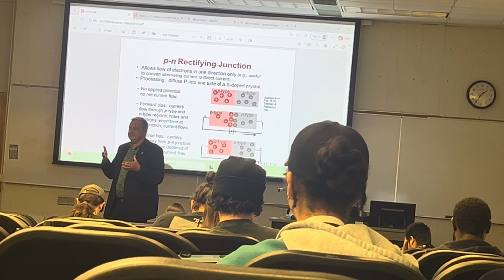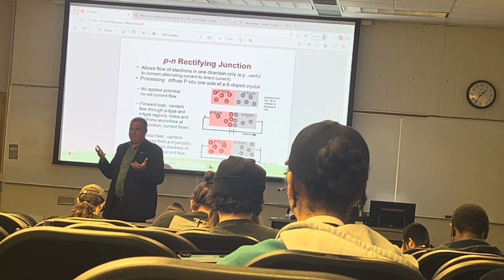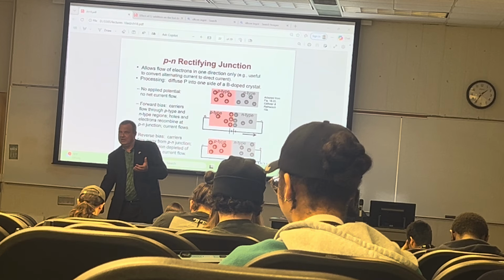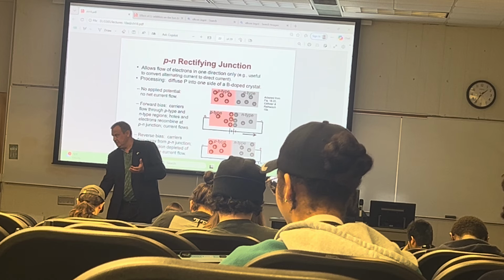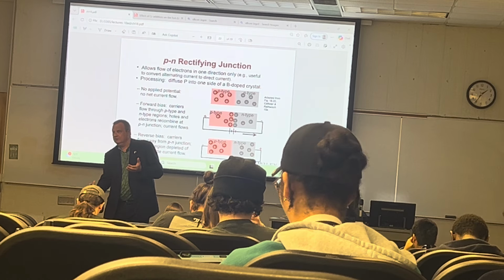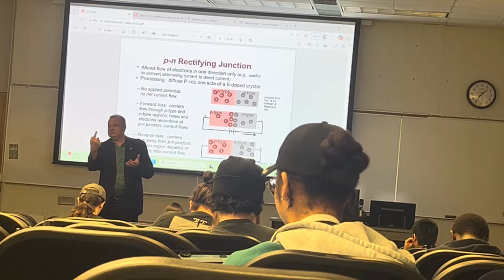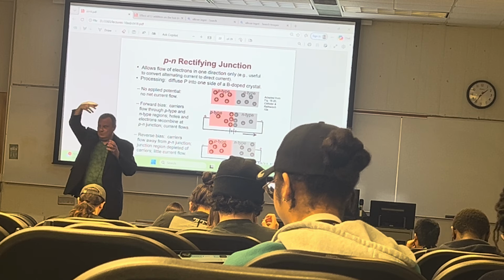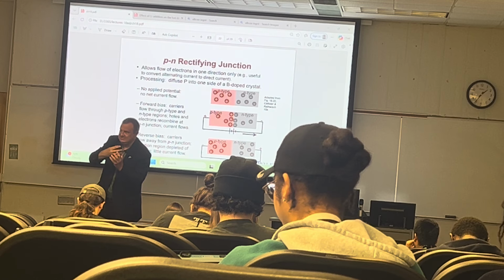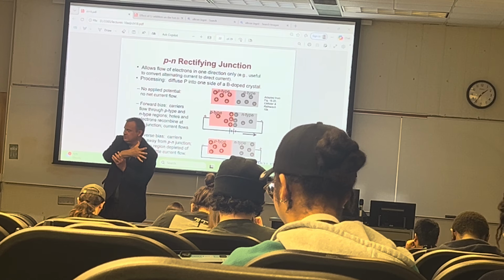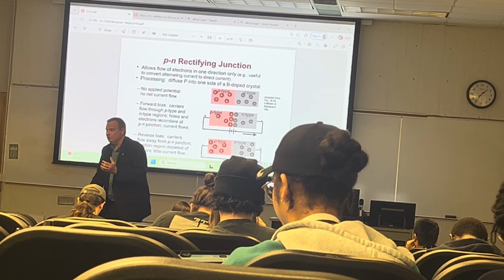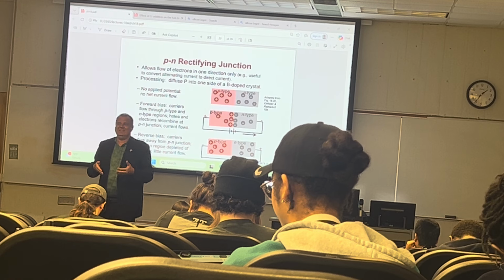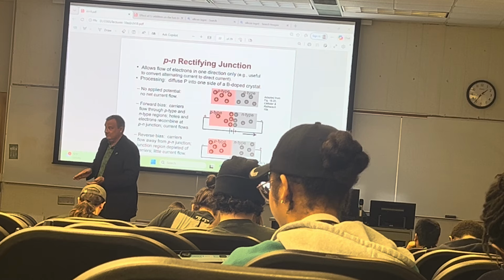So for whatever reason, there's some back pressure. The pipe got clogged, wasn't clean. What's going to happen to the water? It's going to rise up, and it's going to create head pressure. And then it's going to go to the individual AC units. And then the AC unit is going to get flooded on lower floors, and it's going to propagate to the higher floors. So in order to prevent this from happening, there's a flapper valve.